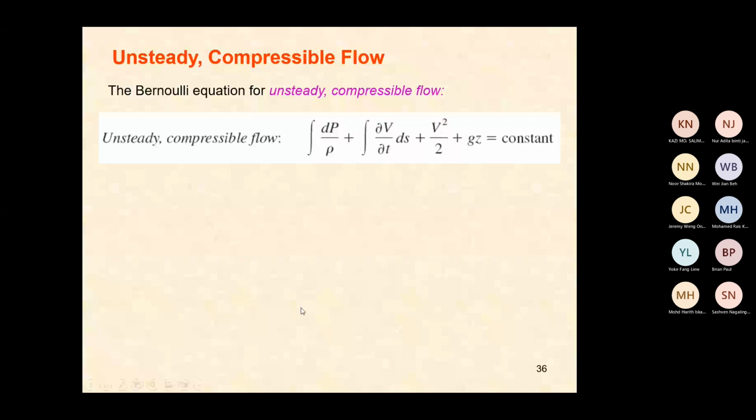So if the fluid is flowing through the tube, then the static pressure is measured after the stagnation point, at the tube inner diameter and the inner temperature of the fluid. So P is the static pressure. It does not incorporate any dynamic effects, and it represents the actual thermodynamic pressure of the fluid, the same as the pressure used in thermodynamics and property tables.